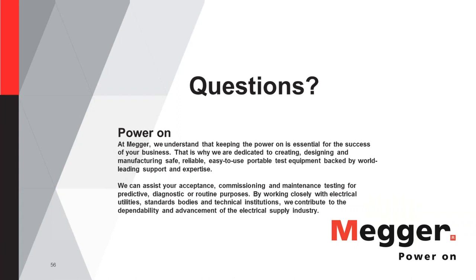So you're having a line-to-line fault, which is just measuring the fault current, and usually all the pickups for the phase overcurrent are decided by the fault analysis. The fault analysis will give you the settings, and the settings are decided by running all the different types of faults. So they run all the types of faults, and then they decide what the settings should be.